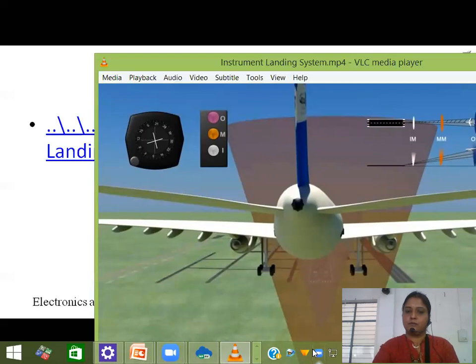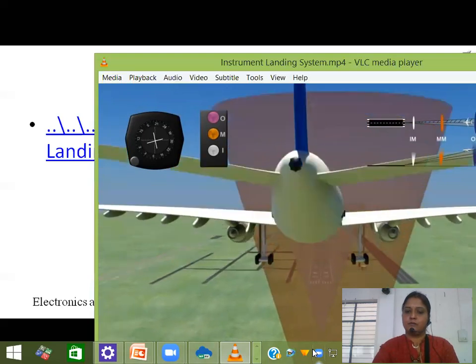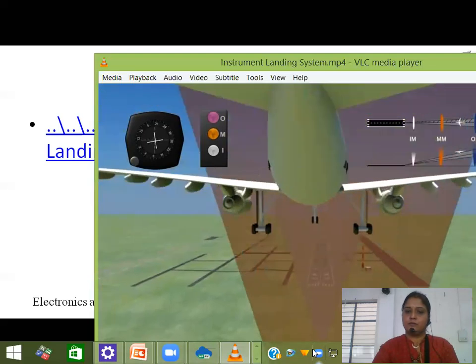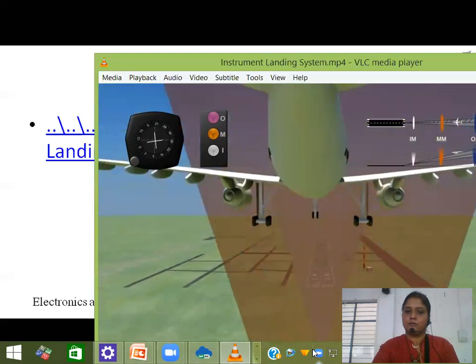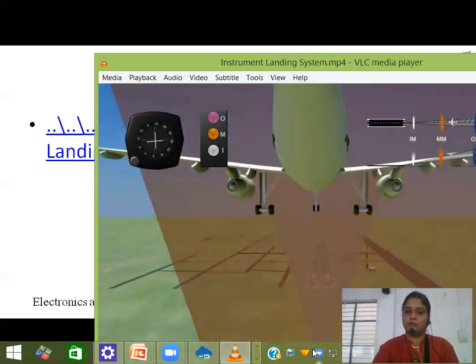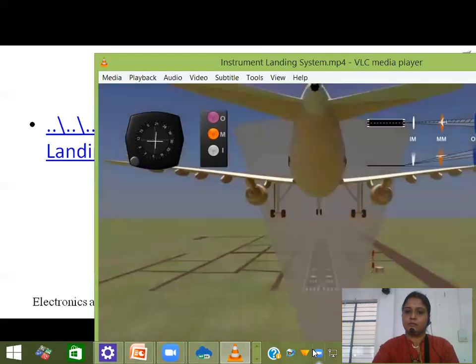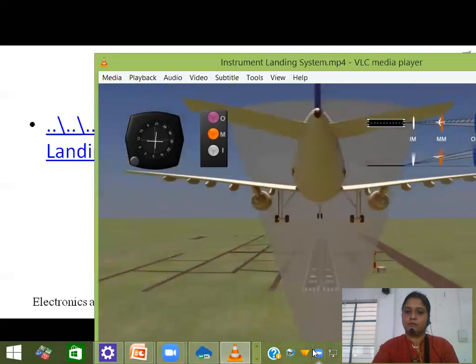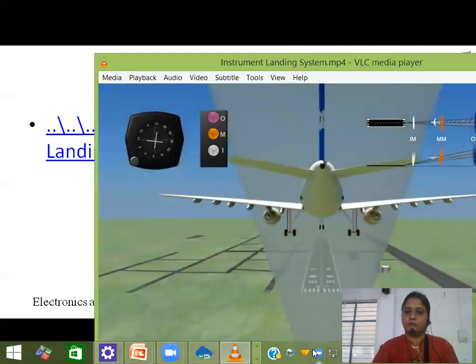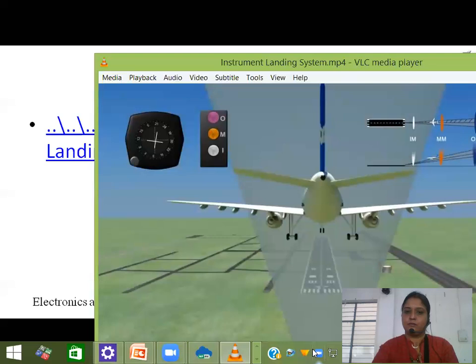The middle marker is typically the location where an aircraft on approach will be at an altitude of approximately 200 feet above the elevation of the landing area. This system enables pilots to visually identify the runway, either by pavement or with the assistance of an associated approach lighting system. This marker's audio signal is a series of alternating Morse code dots and dashes in a high tone.